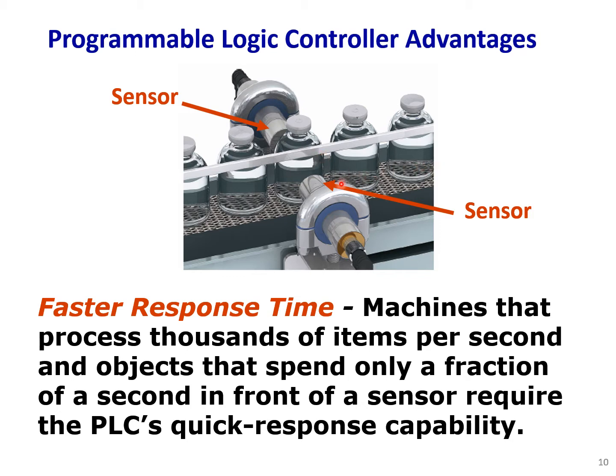If we increase the speed of this conveyor, the sensor sends signals at a higher frequency to the PLC. PLCs usually have a faster response time, and they can cope with the high-frequency data coming from the sensor, but relays have a slower response time compared to PLCs.